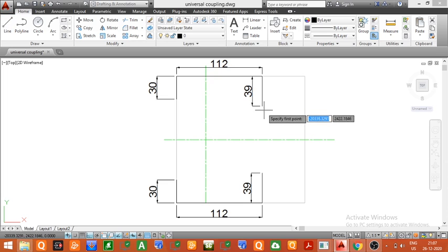Now in the next step, we just have to draw a horizontal line till this end line of the box. Just draw a straight horizontal line till this end line of the box. So now from here to here we will draw a horizontal line, and finally we will join these 2 points by a straight line. So we have joined these 2 points with a straight line. Now we will see this dimension. Now this dimension has to be 88. The total length was 166, whereas the diameter of this hub, this central part, was equal to 88.